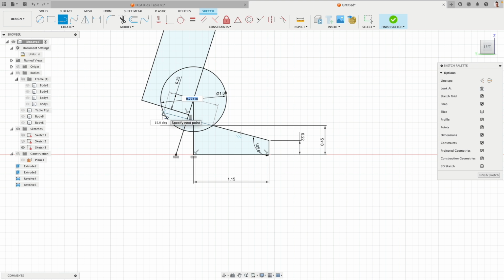If I draw this line a little bit crooked, then I can make these 2 lines parallel. So there I can see now where this piece would later be. And here's another little prototyping tip. I draw these 2 crazy lines, make a construction line, then this line to here I make parallel, and this line to here I make parallel, and then this line to this I make equal. There you can see now what I have. You can clearly see the construction line there. This one actually helps.